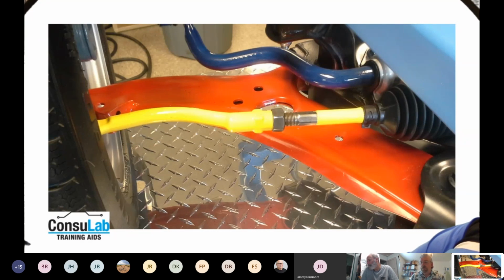The other thing that guys are getting into is correcting the amount of overall bump steer by positioning of the tie rod ends and where they're at for height so that the arcs get closer matched. One of the applications of this goes back into older GM cars where they had the center takeoff racks with really long tie rod ends.